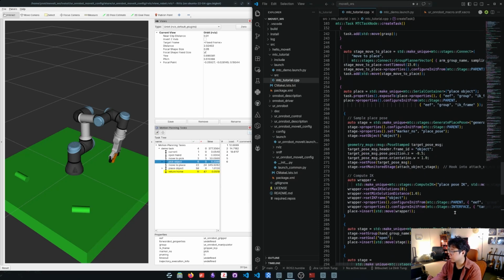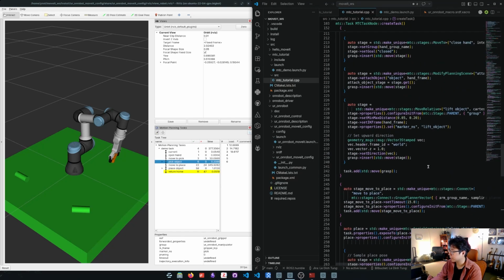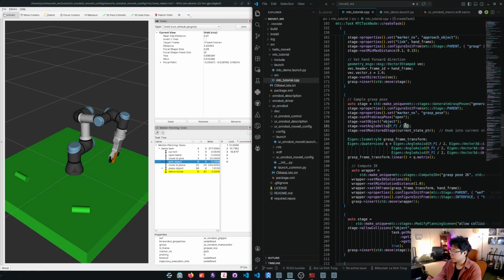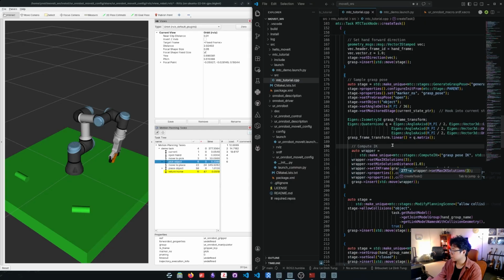All right, so let's have a look at the code for our grasp planning. Here what we can try is to make this a bit bigger. So let's do it at about 5 degrees at a time. So that would be dividing it by 36. Yep, 5 degrees variations. And we will lower the resolutions, otherwise it will take too long to plan. So max IK solution should maybe be 3. And we can keep the placing the same, because I feel like for the placing, it's already nailed that. Okay, so let's see if this will improve the number of solutions that we get.